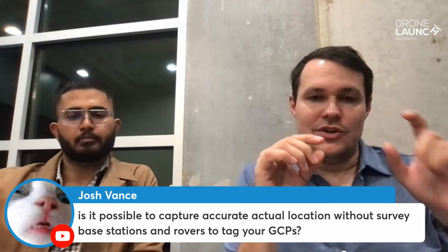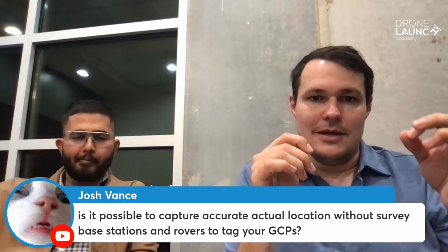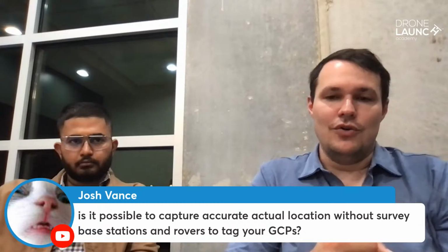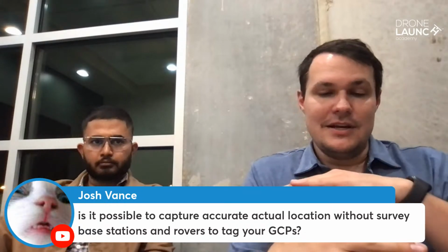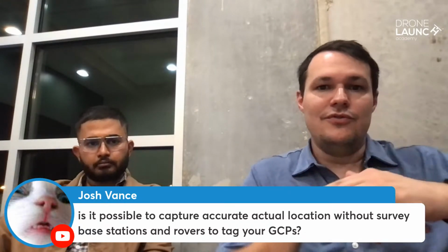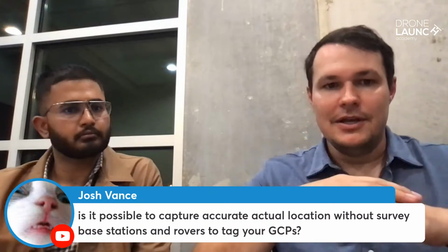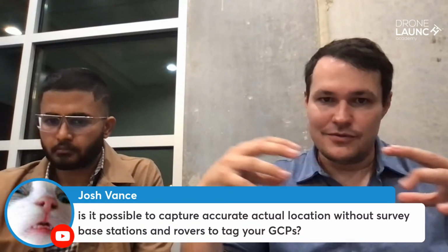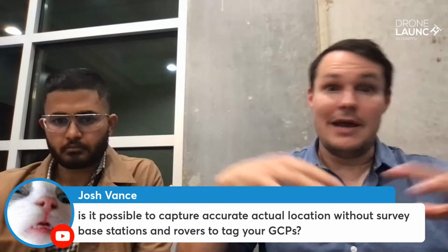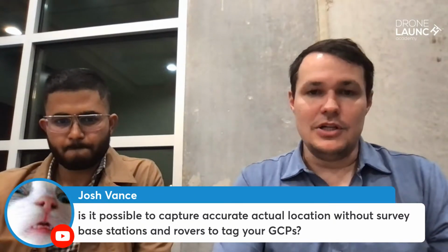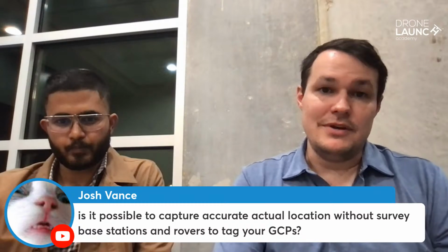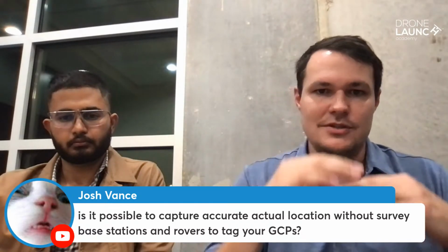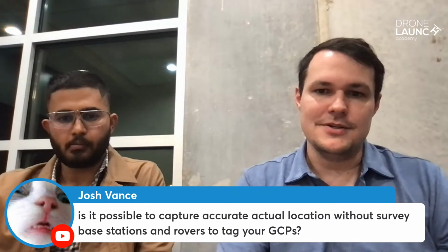And again, you're just using the coordinates from within the Google Maps base layer. You're not out there with the actual rover, measuring. But at least it's going to help you line up so that every time you fly a progression map, those will stack on top of each other correctly, and you can check them on and off and see how things have shrunk or grown or changed without the map jumping all over the place. So it's a loose georeferencing, not survey grade, but more for visual references and comparison of different layers.